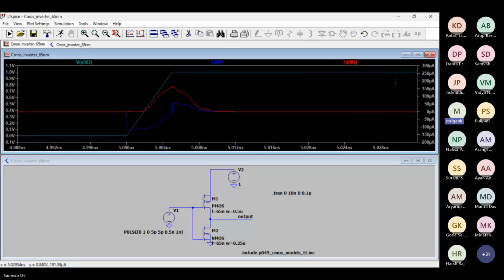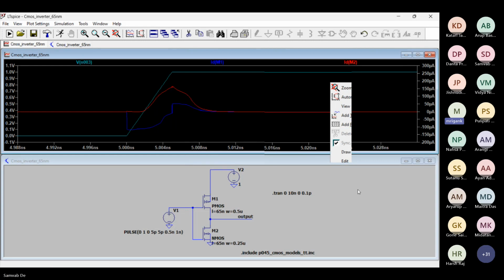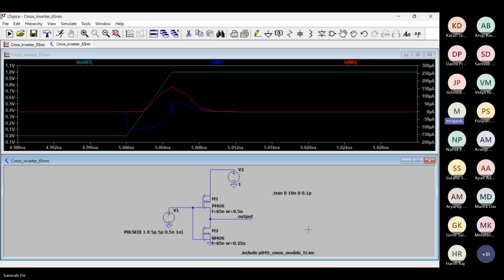That's why you are getting negative current, because the definition for the MOSFET current is downward going, it is positive into the source. But at that node, we are getting a negative current because of the capacitive coupling between the gate and the source. So that CGS factor will lead to that negative spike. Now, if you put